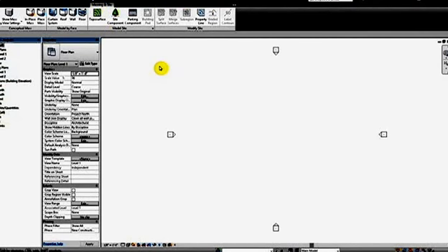Next tab is the Massing and Site tab. So massing is more what you do in the conceptual phase, when you're just trying to get your building massing down and quickly model various forms. It's also used for complex modeling, like a parametric curve or a parabolic curve or something like that. Something that's not typically modeled. And then you can apply roofs, walls, and floors to a mass. But I'll cover that in a later tutorial.